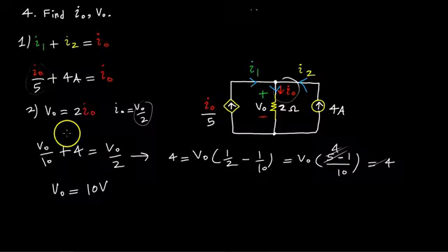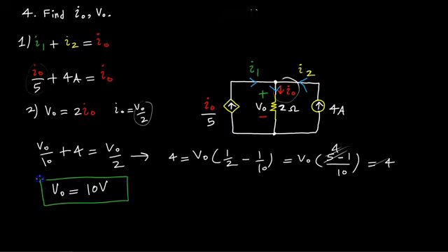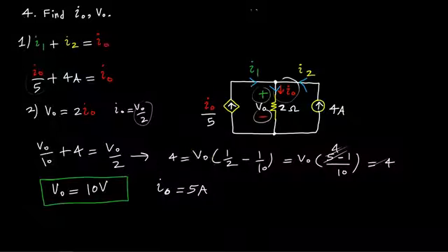That's what I have there across. That's the voltage drop across that resistor. And with it being a positive value, it means that it's matching the polarity indicated. So I'm not going to worry about anything there anymore. Then I'm going to look at I0. I know the relationship between the two, so I0 is whatever V0 is divided by 2, so I0 is going to be 10 over 2, which is 5 amps. And again, it's positive, so the polarities were guessed correctly initially. Okay, so that takes care of that.